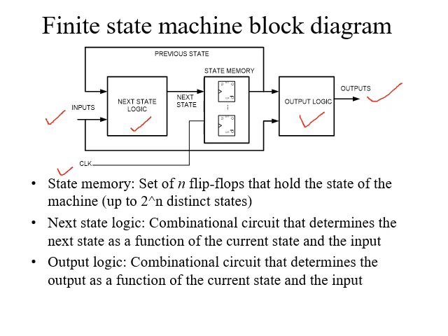Now we have a feedback. So the previous state is also going back through this particular connection, and we get a next state which is stored in the state memory. So we have a memory element also. We can use D flip-flops for storing the bits like zeros and ones. So this complete block diagram shows the structure of a basic finite state machine. These are the various elements present.